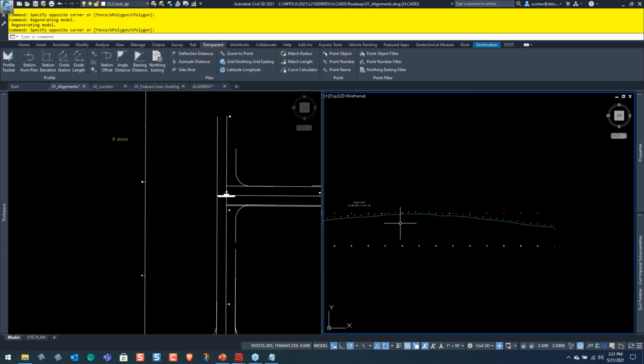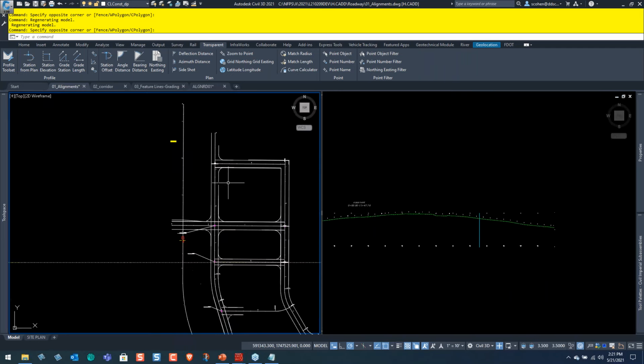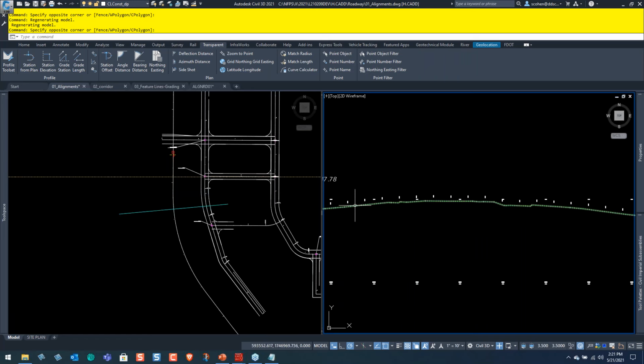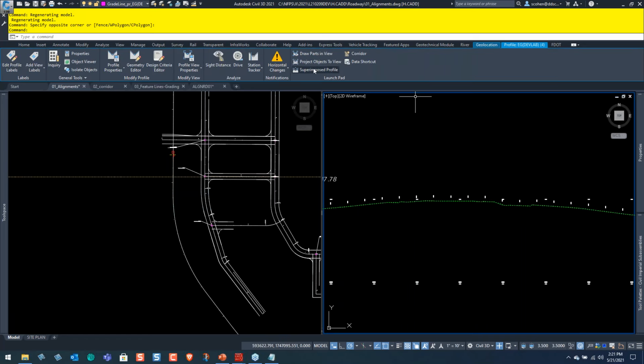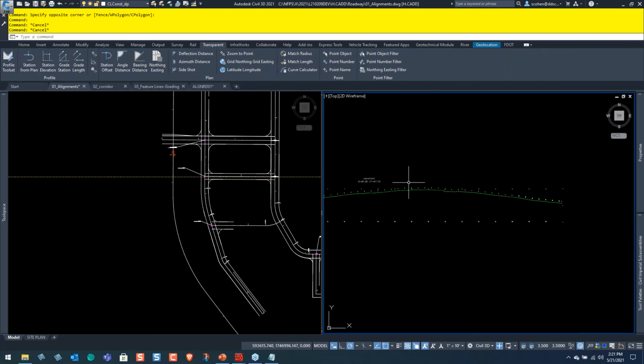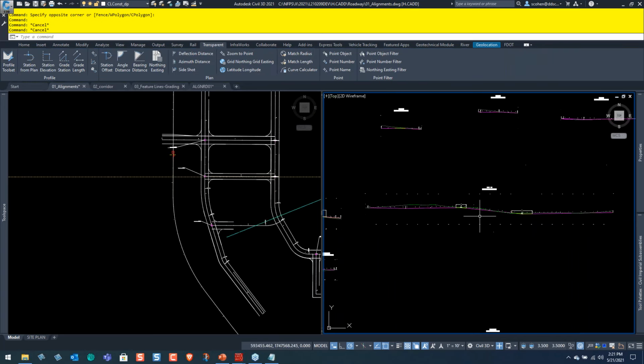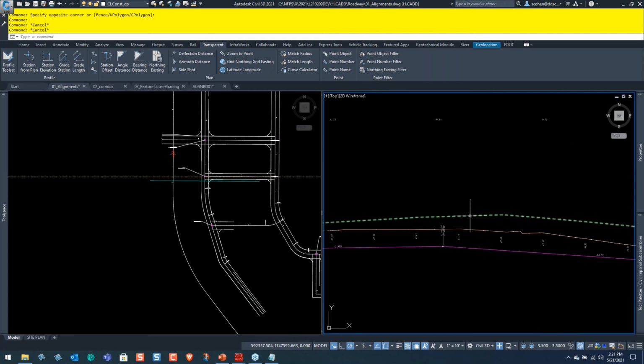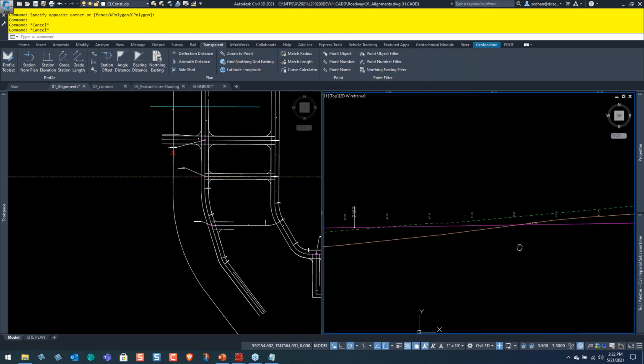I want to actually see this elevation because, if you've ever done site design, you want to know what this will look like. What will this existing elevation look like along my alignment, which is covering the entire part? All I have to do is I have that alignment. I simply select this, and then I superimpose the profile, which is dynamic. It's obviously just existing, and I put it on right here. So here's the cool thing. This is existing ground. Okay, that right there is existing ground. You can see that. This one here is the easement. And I gave it a different style. That way I could actually see what's going on.